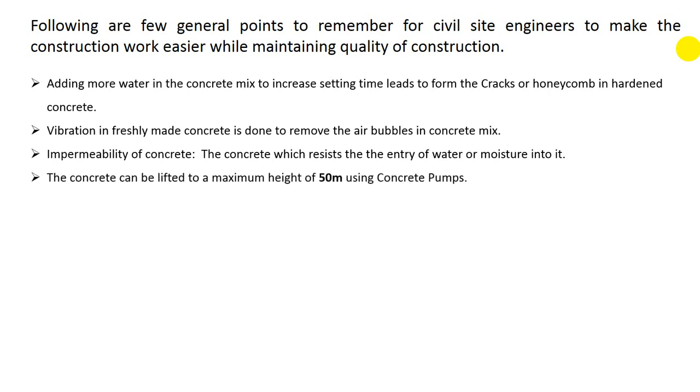Then, concrete can be lifted to a height of up to 50 meters using concrete pumps. I mean, they have concrete pump machinery, and by using that machinery a construction engineer or a construction company can pump concrete up to a height of 50 meters. The curing period of RCC is 28 days. To gain the maximum strength, we have to cure the RCC for 28 days.